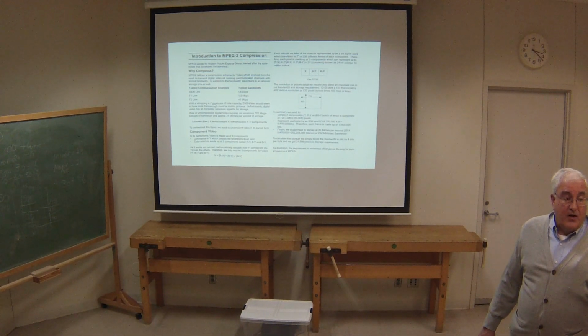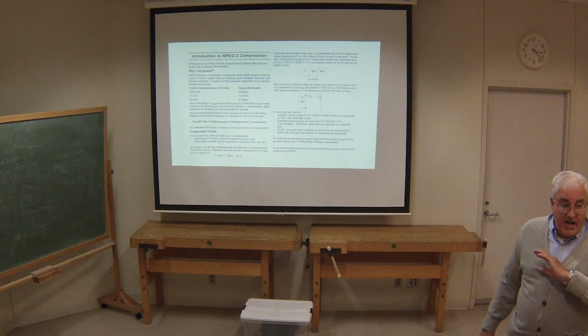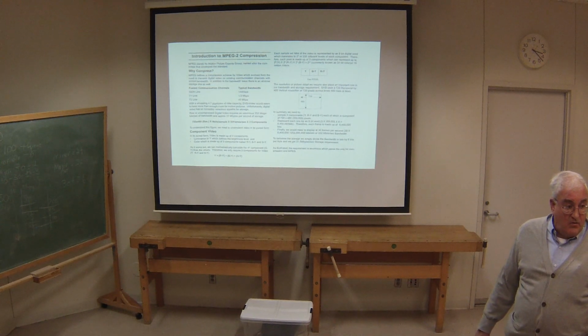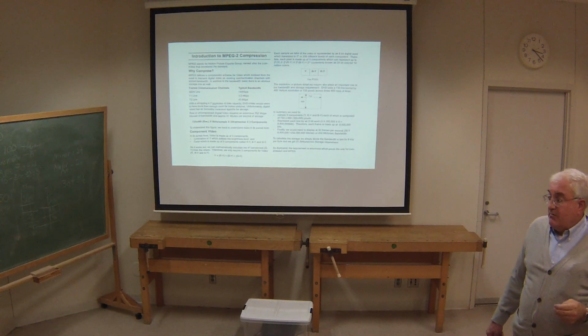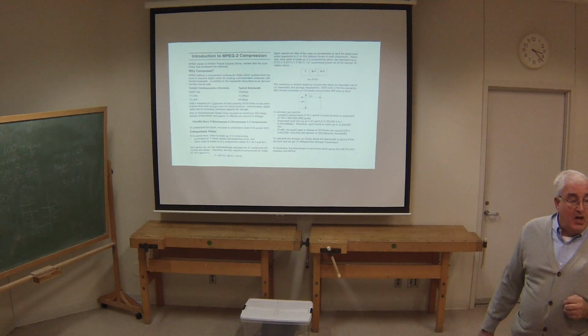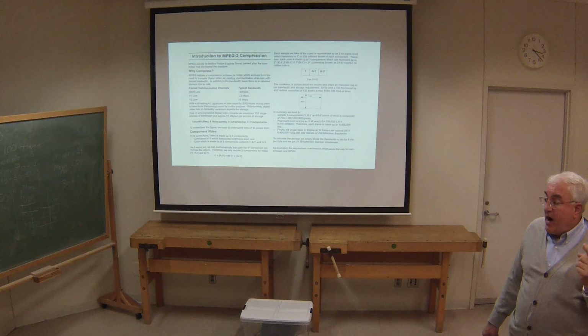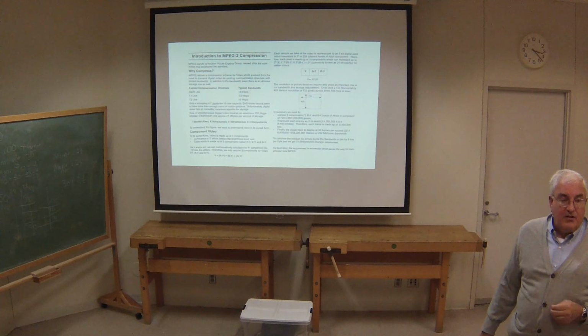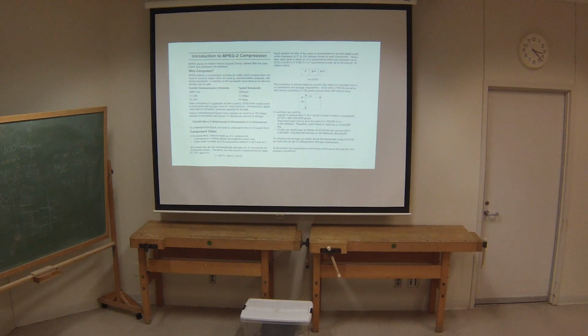And the very first thing that happens in just about any video camera is that you take your red, green, and blue outputs, you develop your black and white signal, which is called the Y signal, or luminance signal, and then you generate a signal called red minus Y, or R-Y, and B-Y.